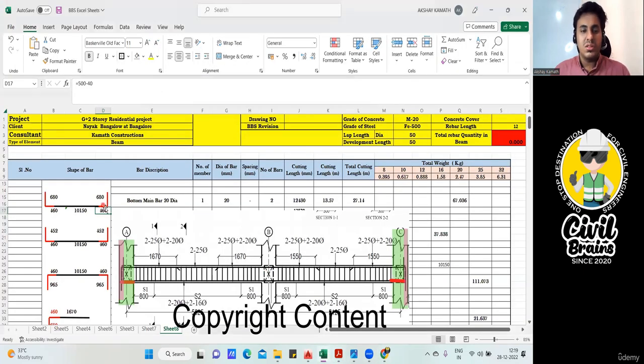This much is clear, no? This is also understood. Now it's very simple. Now we got the horizontal length, and we know that this complete development length is 57 times the diameter of the bar, right? In this, the horizontal length I have got is 460. So if I deduct only the horizontal part of 460 from the complete development length, will I not get this vertical height?